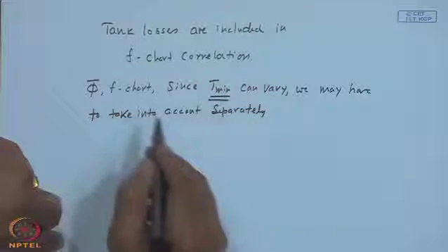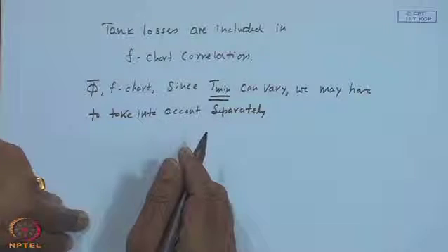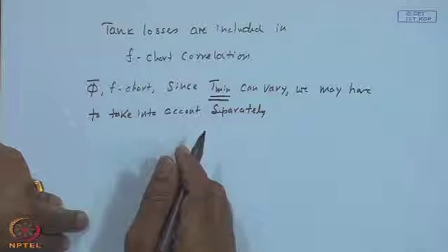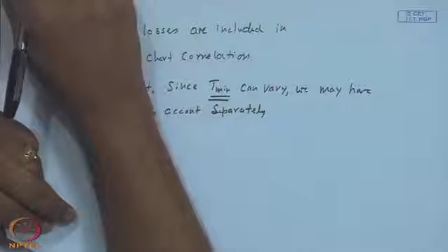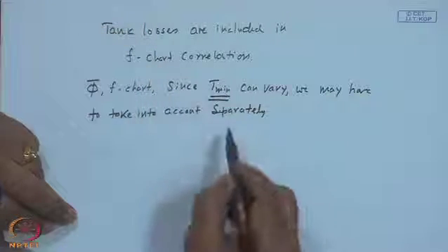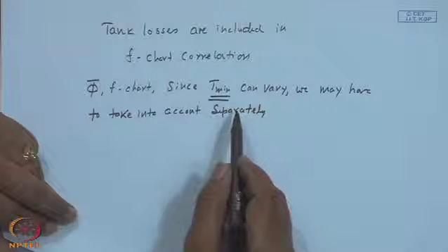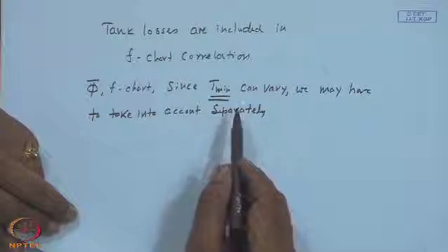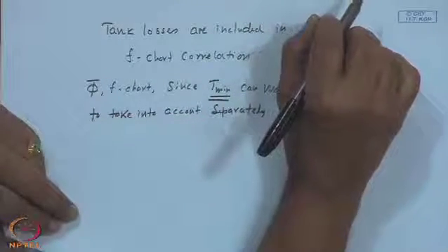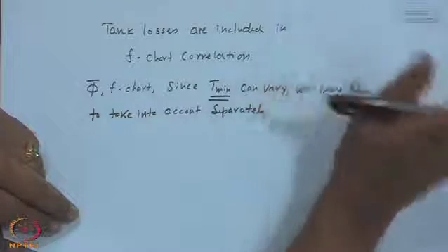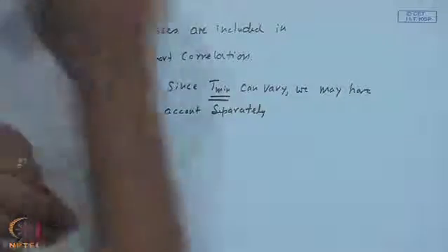Similarly, heat exchanger also, depending upon the temperature and the load condition, its effectiveness and its transfer capability may be varying. So, once again we include the heat exchanger. Indeed, in the F chart method also, though losses in the pipes and tanks are not mentioned, heat exchanger size has been mentioned, and if the heat exchanger size is not the standard size, you correct the variable y as yc by some exponential function. So, the heat exchanger is there in the F chart method also.